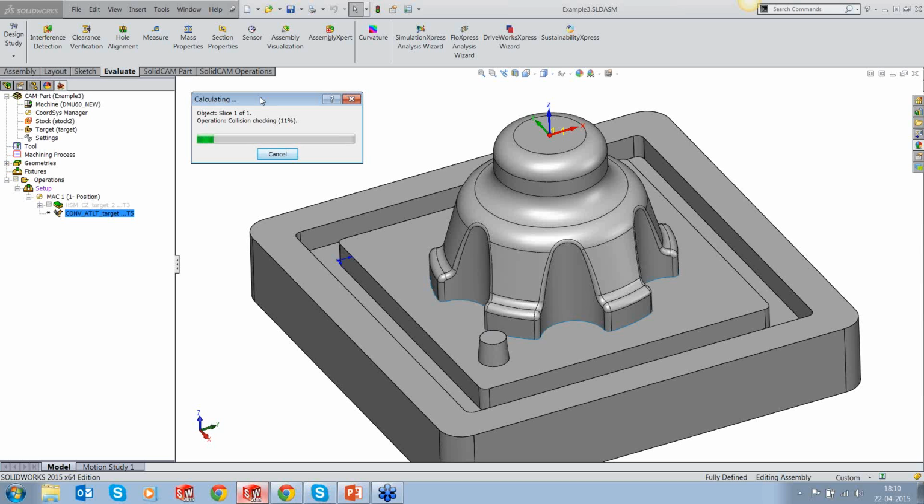We believe that this particular function that you have in front of you, the auto tilt function, is going to be very useful for the mold makers, because let's assume that they would like to cut a core or a cavity with a short tool, and they do have a 5-axis machine, and then it's very useful because they can go really deep without having to use longer tools.